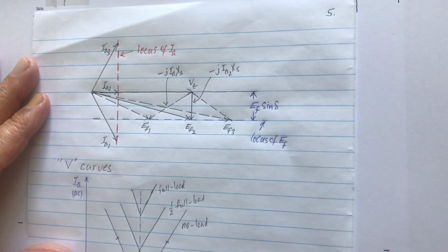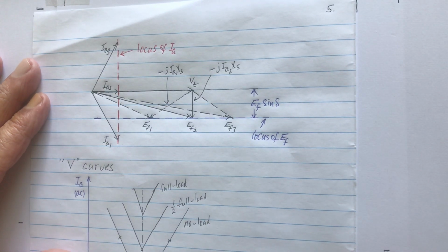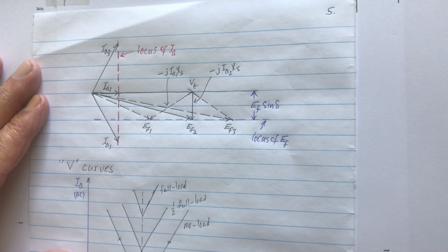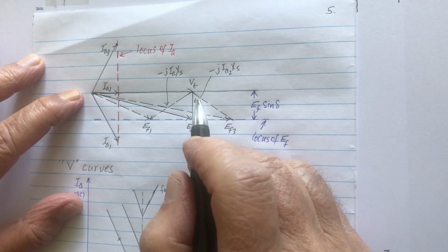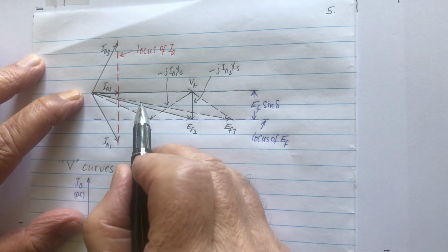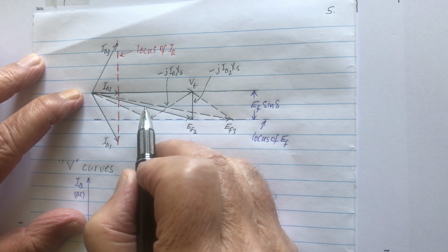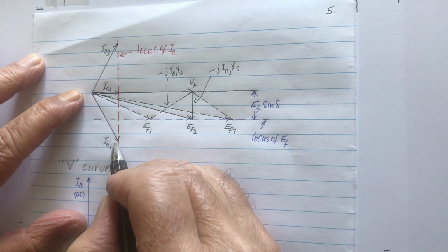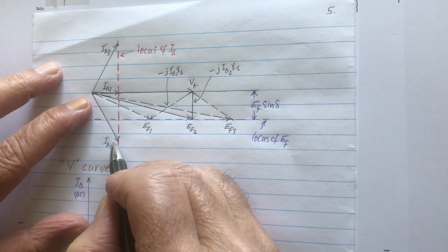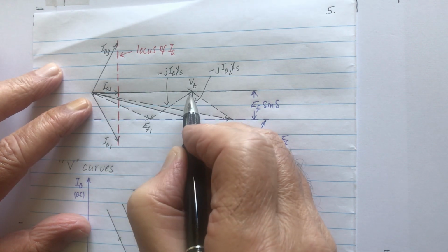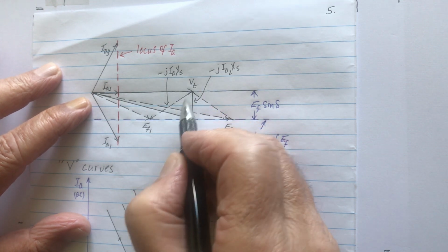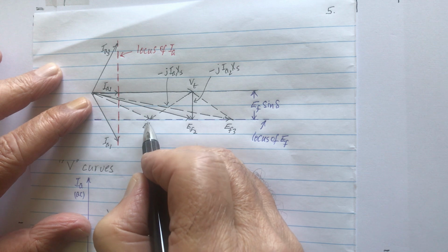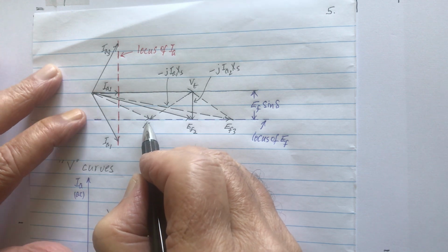This is the phasor diagram for a synchronous motor running at constant power. This is VT. If we take the first case, IA1, lagging power factor, then we subtract jIA1 XS from it, and we have EF1.